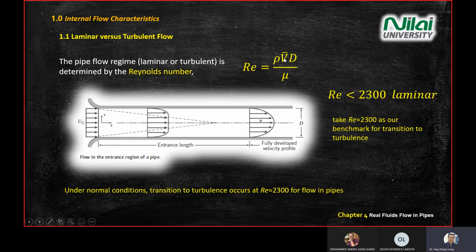So once you find the velocity, there will be a particular section asking you to explain the flow regime that you have. So after you get V, you calculate whether you are having laminar or turbulent flow.